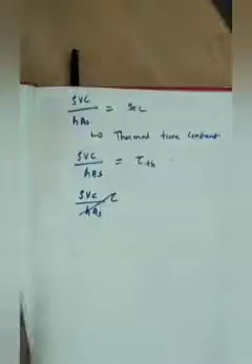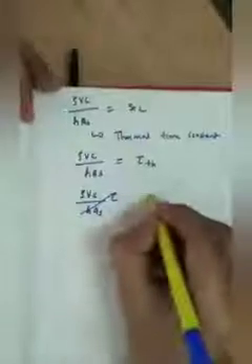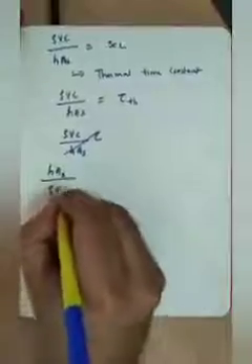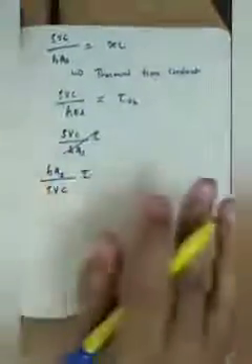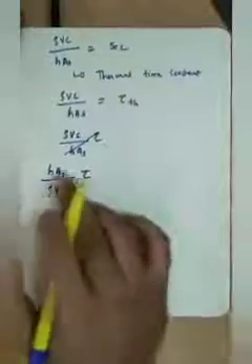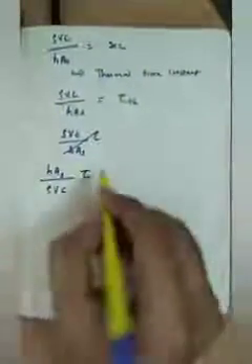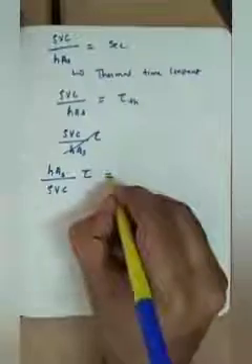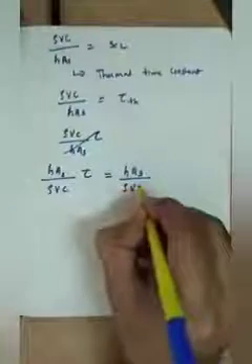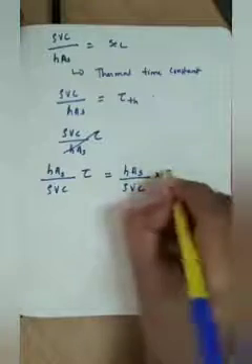Now we can discuss the quantity HAS by rho Vc into tau. Of course, this is a dimensionless quantity because the dimension of tau is second, and the dimension of HAS by rho Vc is 1 by second. So this is a dimensionless quantity. I am doing some rearrangement for this quantity, that is H into AS by rho Vc, into tau.